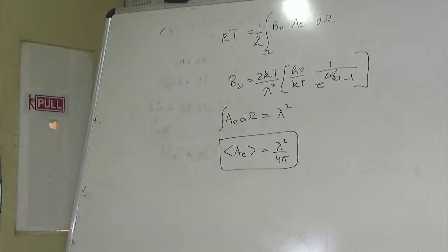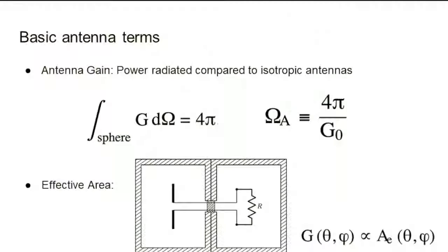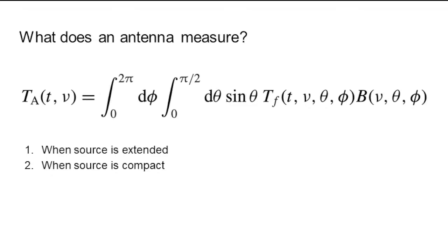We talk about collecting area when we think of antenna as a receiver, right? So it's receiving some power from a resistor. But when we talk about antenna as a transmitter, the gain becomes important. So in some way, they are actually almost the same quantity. They are just factors of 4 pi here and there. But overall, they are not different at all. Though again, dimensionally, one is radiation pattern, one is a collecting area, but they are almost the same quantities in radio astronomy. Okay, so we'll go to this part and then we'll simply look at some of the telescopes.